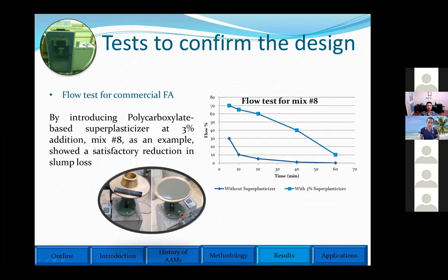When you develop alkali activated material and test it for the slump, for the workability, you can see that it's perfect, as you can see in the video. But after some minutes, after half an hour, after an hour, you see that you have a slump loss. It means that initially, for example, you had 7 inches of slump, and after half an hour, it turns into 0 slump. It means it hardened very fast, and you cannot work with it after half an hour.